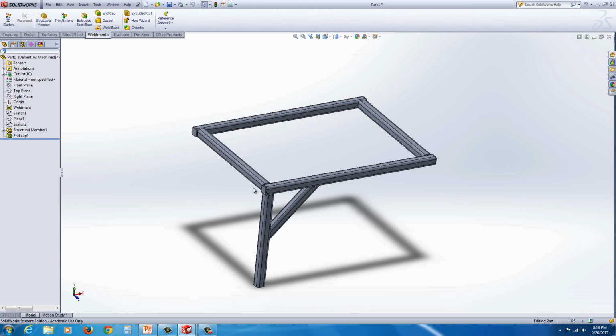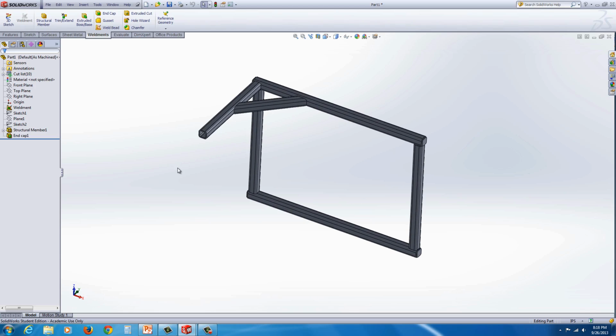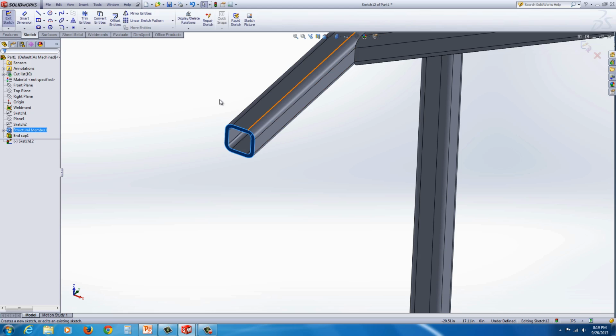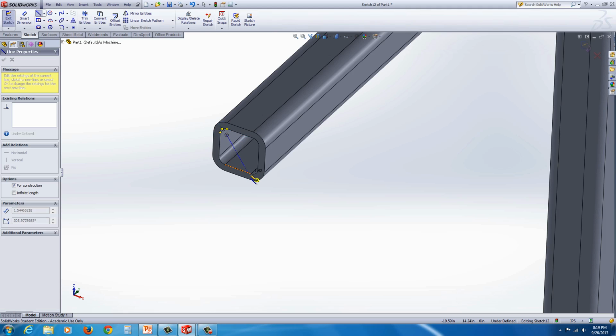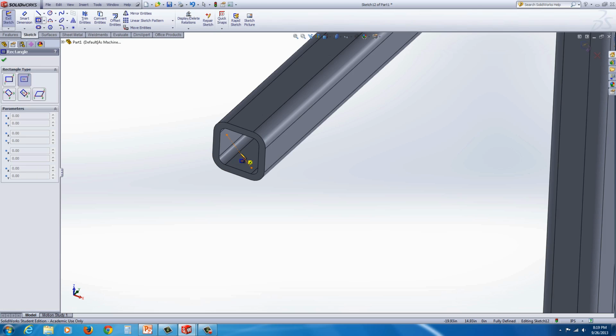At this point, we're going to go ahead and add some feet at the bottom. So select the bottom face, start your sketch. I just want a centered foot pad here, so I could find the edge until it wakes up the center point of that. Find the edge here, wake up the center point so it's diagonal, and hit escape after you select there. Now we have a nice area where we could go to the center rectangle, lock it into the midpoint of that line, and drag out your rectangle.